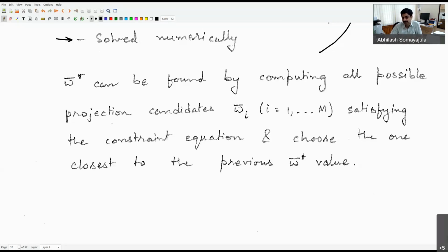We looked at the vector field guidance law. Then we looked at a special case of that, our look-ahead proportional LOS based guidance law, where the only difference was that when I was far away from the path, I would be coming perpendicular to the path in the proportional LOS scheme, whereas in the vector field guidance, I can specify at what angle I should be coming in.